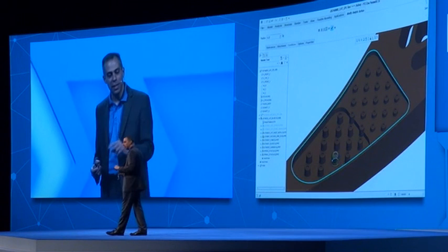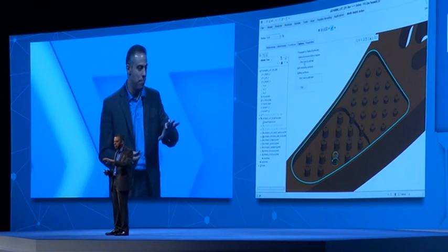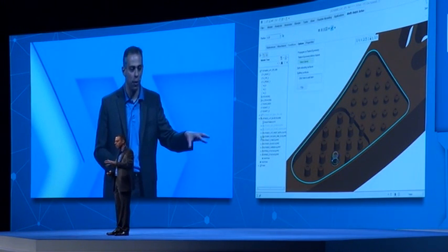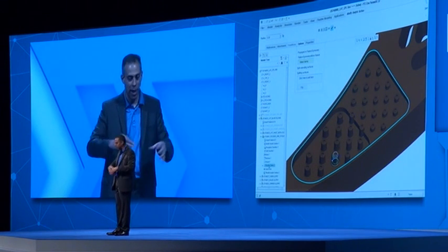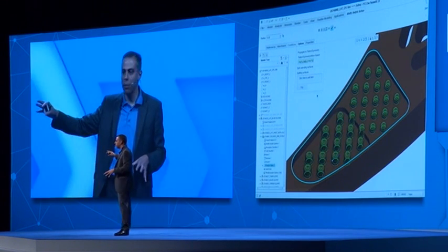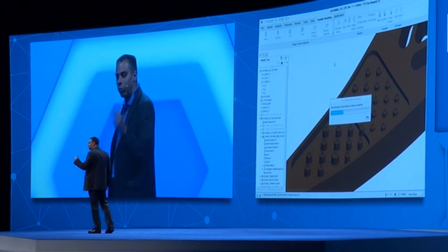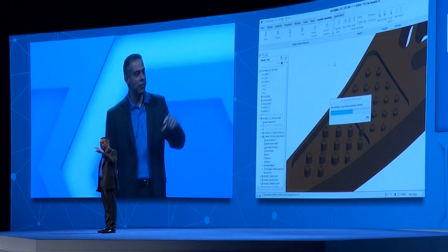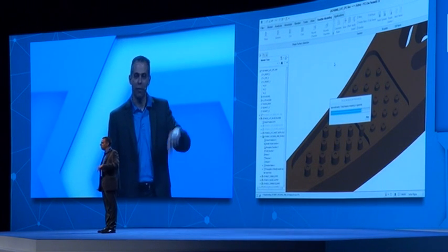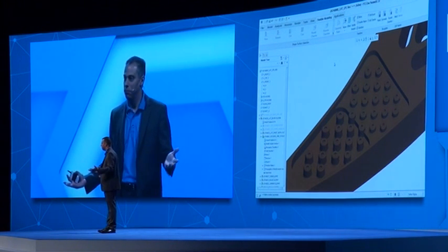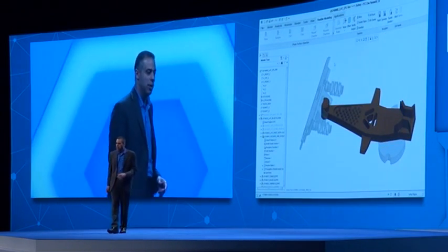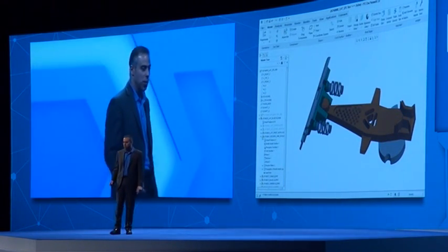The other thing you're seeing here is that I've chosen a member towards the end of the pattern group, and I'm changing its diameter, and I'm propagating that change to the rest of the pattern members. That's not unique to flex modeling. In Creo 3.0, you no longer have to find the leader of the pattern to do a reference pattern. You can do it from any pattern member. So that's a nice improvement across the board. It actually applies really nicely in this video as well.